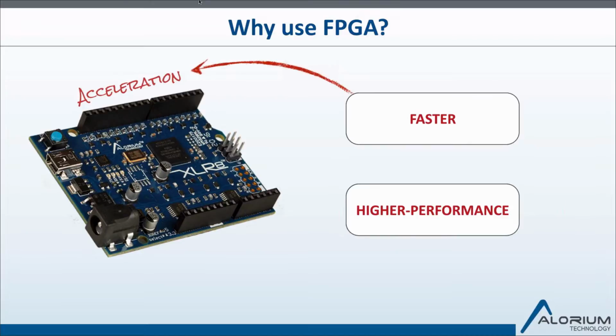And it's really not. I mean, it's related, but what you get when you move things into hardware or you run it on an FPGA is this notion of offload from the processor itself. And this is something Brian will actually demonstrate pretty well with some statistics a little bit later: if you can take that functionality, particularly if it's burdensome to the microcontroller or to the processor core, and push that onto some custom hardware, now you're talking about freeing up that processor again to do other